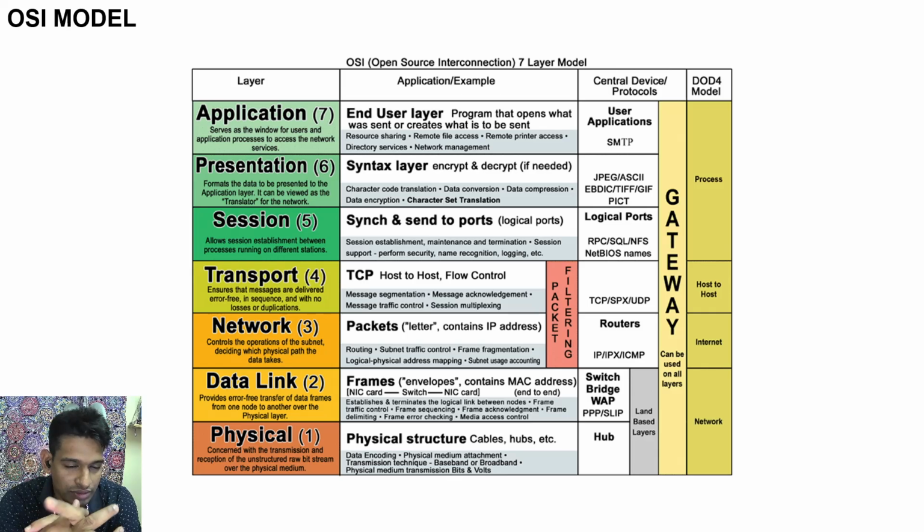So basically, I'll go back to our UART concept. So what does the UART say? The UART says that TX has to be a separate line, RX has to be a separate line. You have to send a start bit, you have to send a stop bit, and your data can be 8 bits. So that is a physical restriction or a logical restriction of sending data over a serial network, UART.